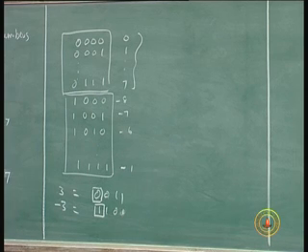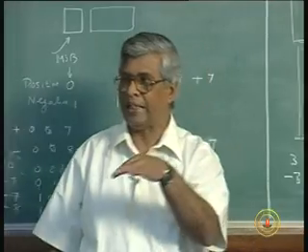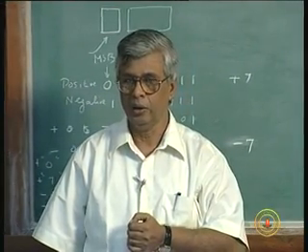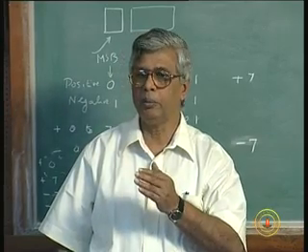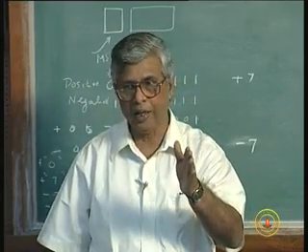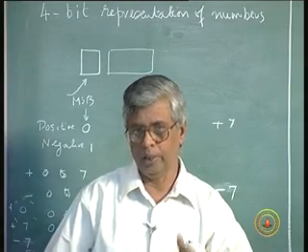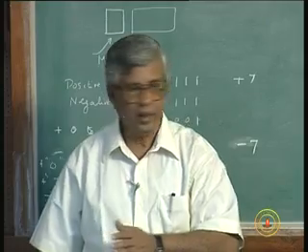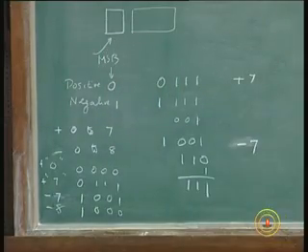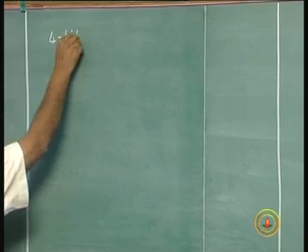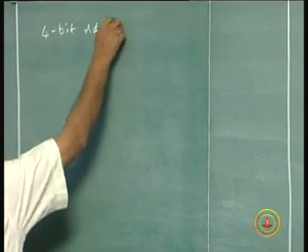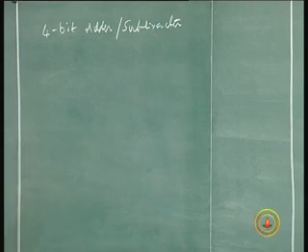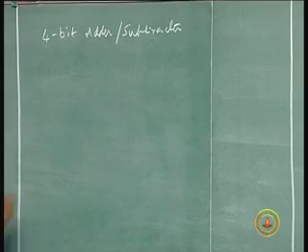Now, if you look at our addition, subtraction being the 2's complement addition, which we showed in the previous lecture, and 2's complementing can be done by passing the bits through an exclusive OR controlled by a bit which will decide whether an inversion is required or not required. Then I can draw a general 4 bit adder subtractor using